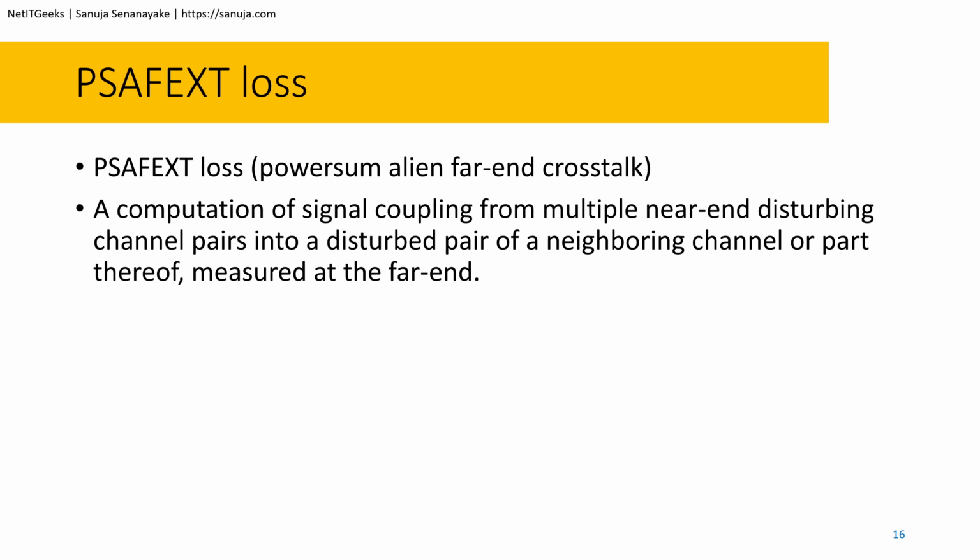Okay, so in this one, if I give you a little bit of background, unwanted signal coupling from one component or channel or permanent link to another is defined as alien crosstalk. So that's what alien crosstalk is. Since alien crosstalk is an indicator of differential, or what we call balanced, signal coupling, alien crosstalk cannot be adversely impacted by common mode noise. Then we can go into depth on how alien crosstalk works and how it interacts with things. But for today, what you need to understand is these definitions.